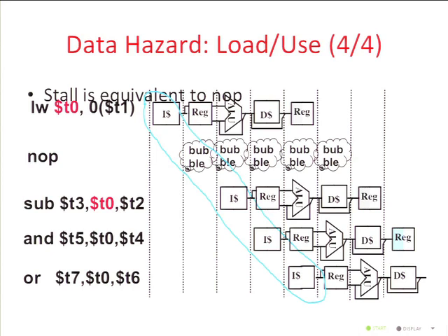At this point, we're going to have the address. We're going to read from memory. I guess the question is, we're going to forward from here. Sorry, we're going to forward from here to the ALU. And then we do have to do something to make sure that it works correctly. But we don't actually have to write the register. We can forward to the ALU here. And we can write the register here if we needed to. So I think we can get it to work, but I agree, you need to draw the arrows in correctly here.